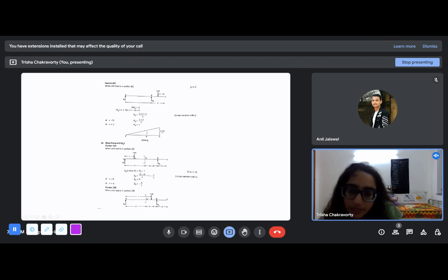When we put the 1 kilonewton here, we get this expression SD is minus X by L. How are we getting it? We will just take the shear force at this section. We are coming from the left side. So RA is upwards and 1 is downwards. So SD is RA minus 1. And the RA expression we have already found out. You have to substitute that, of course.